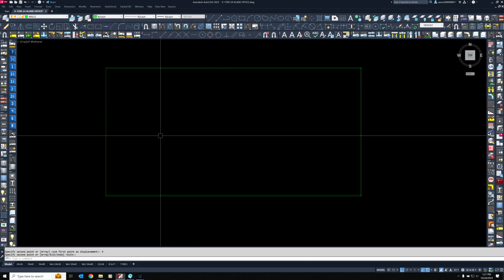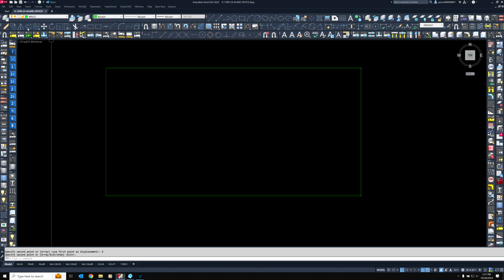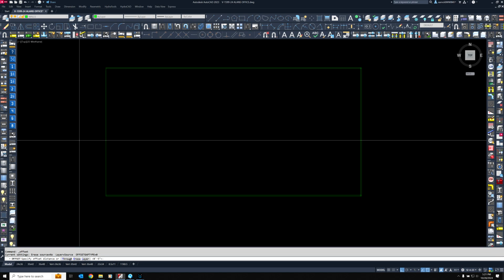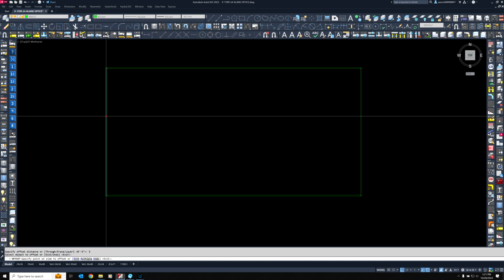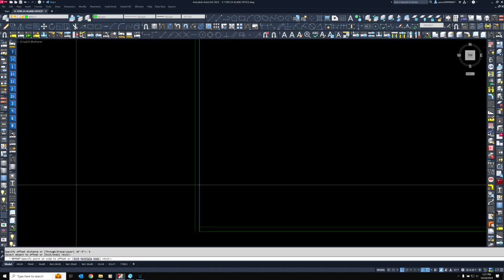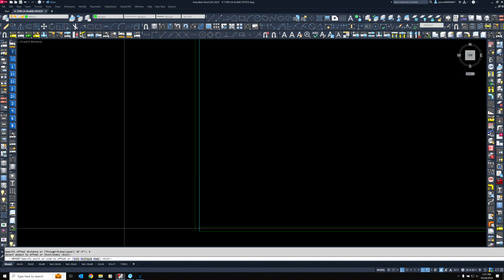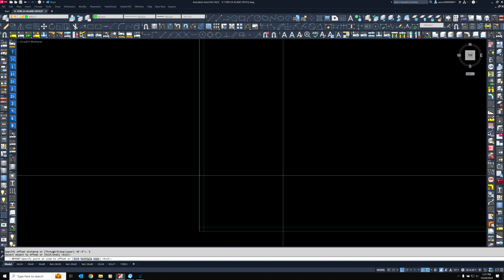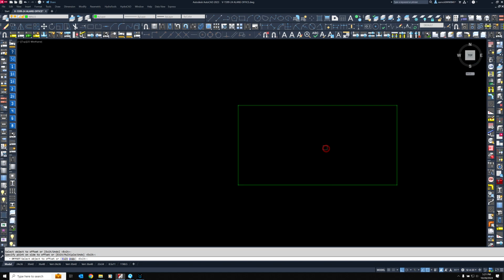If you don't want to copy, the other tool for this is Offset, which is right here. Left click on Offset, specify the distance down here. We're going to go ahead and make sure it knows 5 inches. Now it's ready for you to pick the object, and as soon as you pick it, it's waiting for you. Make sure you can see that. It's waiting for you to tell it which side to go. And in this case, we're going inside.